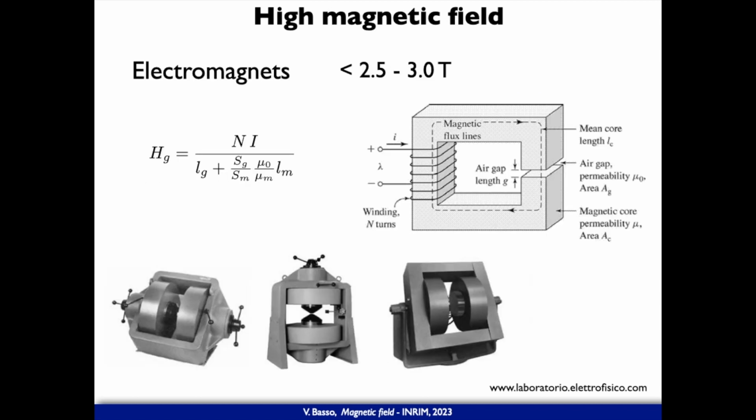To produce magnetic fields at such large values is not that easy with solenoids or with coils. So one very practical way is to use ferromagnets, so to use iron cores like that one, to have windings around the circuits, where we have a high permeability material, that could be iron for example, and then to concentrate the field in a gap.